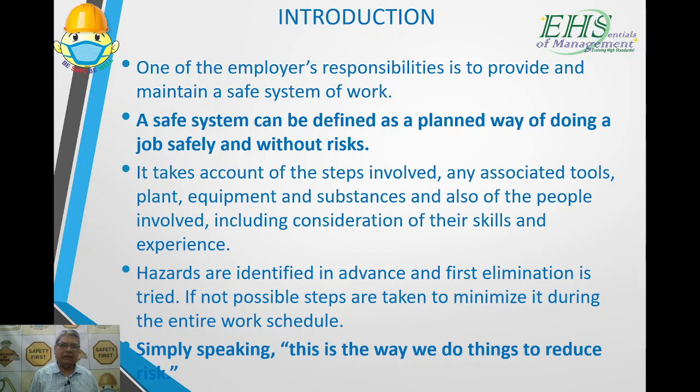Now, a safe system of work is required for routine operations also. There we have the hierarchy of control, and the methodology or the SOPs, instructions and so on. But in case of non-routine work, it is very difficult to decide upon the standard operating procedure or many of the controls which you establish. Say if you are working on the maintenance of a machine, you remove the guard, you disable the interlocking arrangements, right? So here the work becomes more risky, and here we need more precautions in terms of a safe system of work.